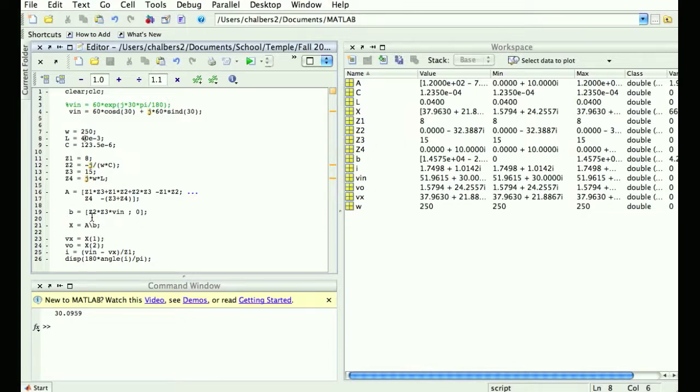In fact, I will give you this, though. I'm willing to bet that if you could look under the hood on Circuit Lab or Multisim or any circuit simulator, how does it know what the answer is? It's doing this. If you were to write a circuit simulator, there would be the graphics layer where you drag and drop the circuit elements. Then there would be another layer where it takes those circuit elements and makes a system of equations.